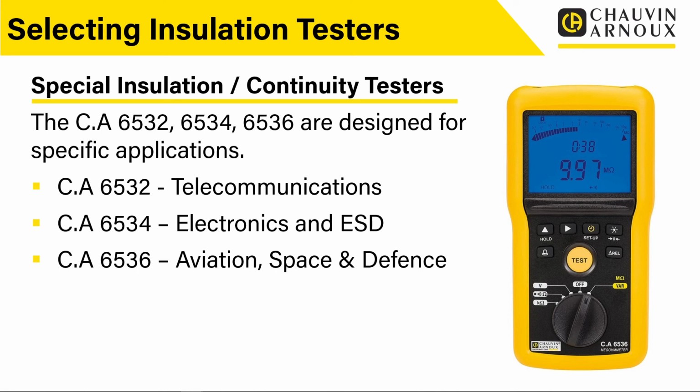And then going maybe a little bit more specialist, we've got the 6536. The 6536 does insulation resistance testing at anywhere from 1 volt up to 100 volts, and you can select that 1 volt at a time. So if you've got a specific application where you needed to do the test at 67 volts, it would do that test at exactly 67 volts, and that would be repeatable.